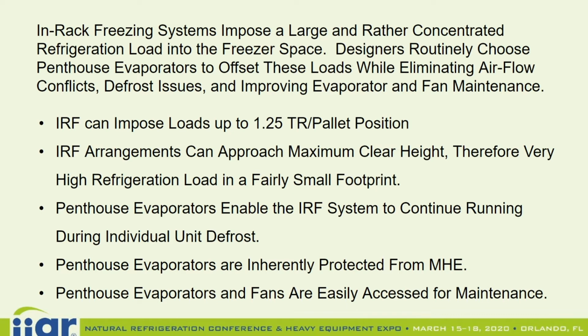And then clearly, penthouse evaporators and fans are very easily accessed for maintenance. In-room evaporators pose much more of a challenge. With a penthouse evaporator, a good refrigeration technician will defrost it, warm up the box, and then go change a fan, which is really not an option when you have aisle evaporators or in-room evaporators.